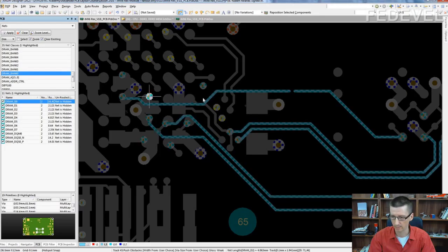Then this one. And you can see I'm using a special mode during this routing which can push tracks. Can you see that? Here down in the status bar you can read what mode I'm using. It's called push obstacles. Press Shift R, you can change the mode.